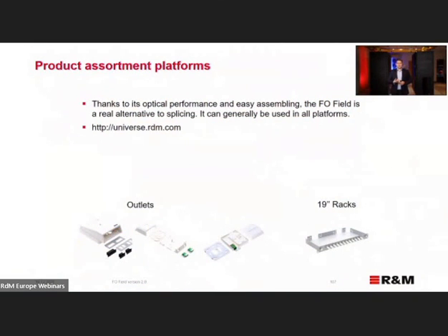Thanks to that, the connector is installed without any special tools and without any special termination tools. It can be installed anywhere, in places which are not as accessible as a typical LAN cabinet or a typical outlet. So this is a big advantage. Another advantage is that the products into which this connector can be put can be really simple. No sophisticated outlets with storage for fiber are necessary. Just a simple outlet. Even outlets for copper connectors can be used here. Then we need to remember not to leave too long a fiber going out from the cable, and that's it.